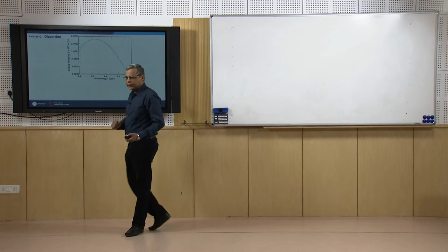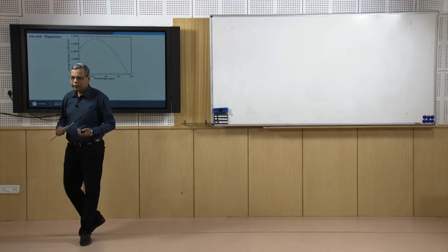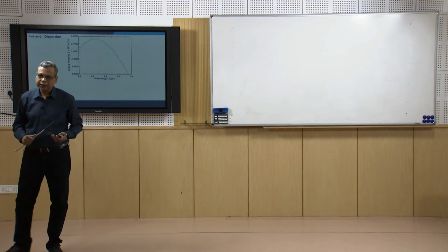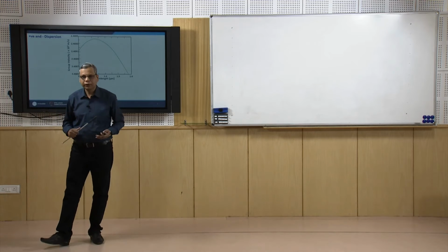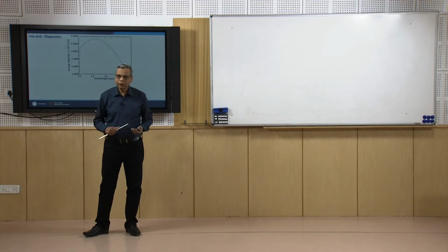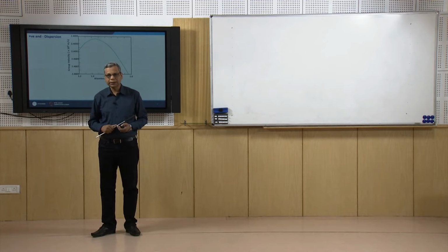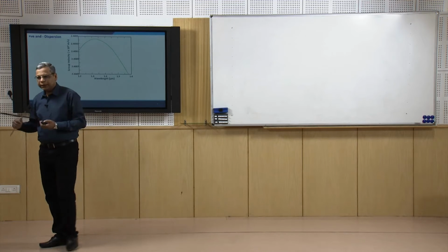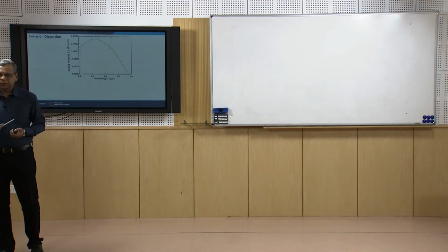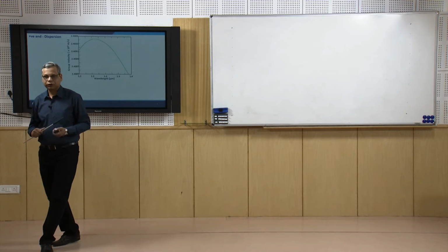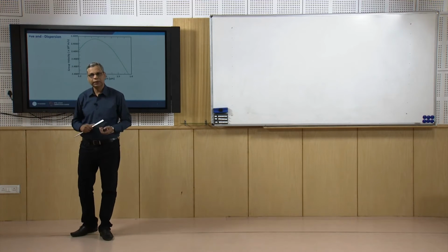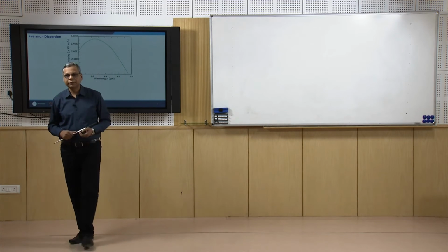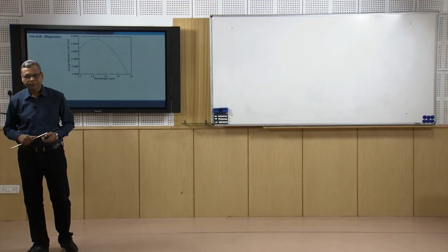To understand this, first of all I should understand why the broadening happens. The broadening happens because the spectral components have different velocities. The mode which is excited at different spectral components has different velocities. Now, when these components have different velocities, I can have two possibilities. One possibility is that the shorter wavelength components travel faster than longer wavelength components, and another possibility is that longer wavelength components travel faster than shorter wavelength components.